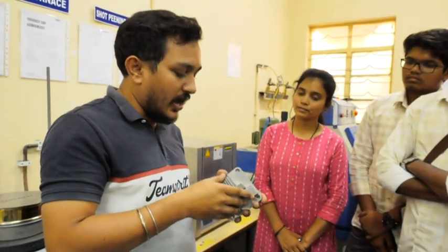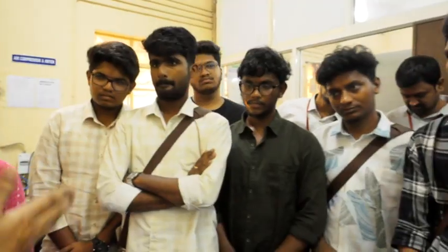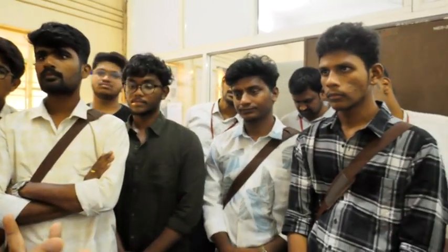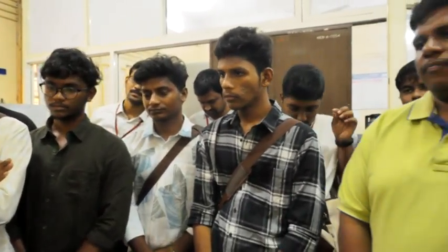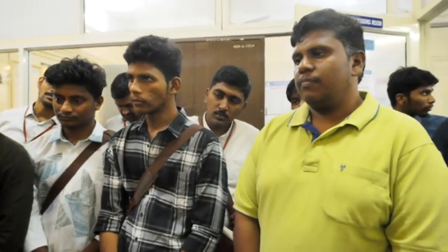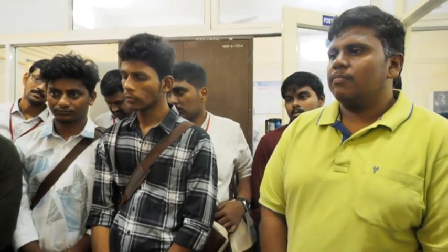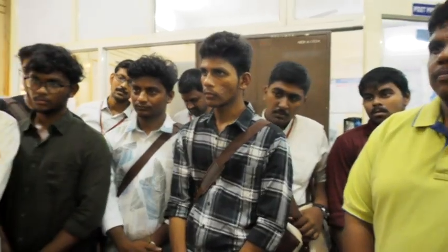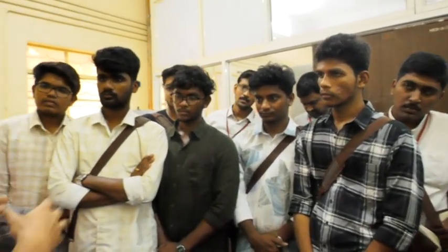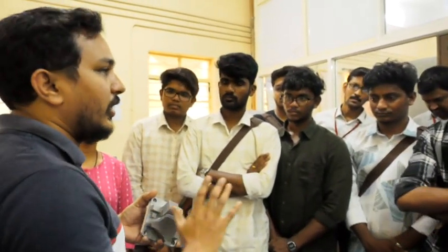So after this, we will be cutting and removing the samples from this build plate using wire EDM. I hope you guys have heard about it, right? There will be a wire of thickness 0.18 mm. Through conductivity, it will remove the parts from our build plate. The best possibility to remove additive samples from the build plate is wire EDM, I can say,